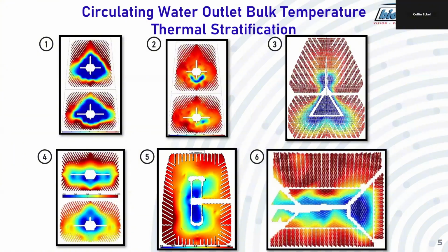Image 1 on the left shows a stagnant zone, which is caused by high air leakage, or conversely, low pump capacity. In this situation, the air builds up, increasing condenser pressure and gas density until it reaches an equilibrium that is dictated by the vacuum pump capacity. The right side shows air binding, where a pocket of air sits in the condenser as steam flow pushes it toward an area away from the air removal zone. This type of air storage will exist at any level of air leakage into this condenser.